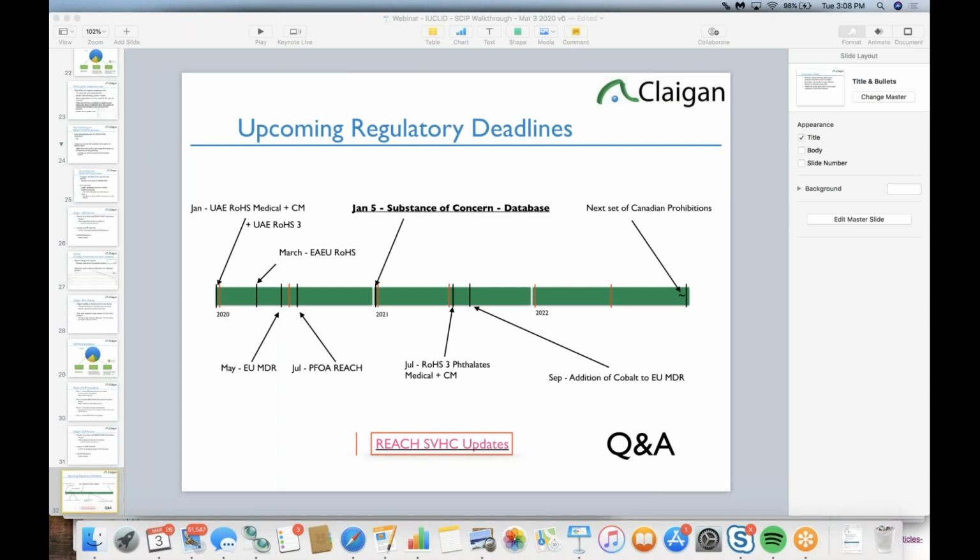So for closed cell foam, so cell foam you can't blow through, it uses ADCA, and it consumes water, and with heat, it creates nitrogen bubbles and a little bit of CO2 bubbles, and it bubbles or foams the polyethylene, and that creates like the closed cell polyethylene foam, like your pool noodle. So if you take your pool noodle, which is a closed cell, and you try to blow through it, you'll just go blue in the face. Those are closed cell, air won't pass through it, and those cells are created by ADCA. And that's usually residual. So one of the most commonly enforced SVHCs is actually what creates closed cell foam. Your polyurethane foam, like in your furniture chair, is open cell and doesn't use ADCA for the most part.